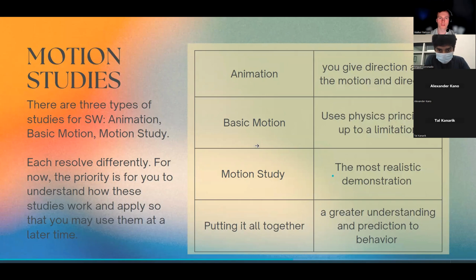okay, give me 1 second. Motion studies are basically the way that we predict what our assembly is gonna look like. The main reason I added this is because, for those of you that are continuing on to hack with us, it's helpful to have motion studies understood because you can predict the movement of whatever it is that you have to design, or test what the environment is going to be on it.